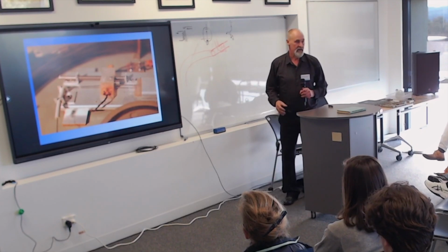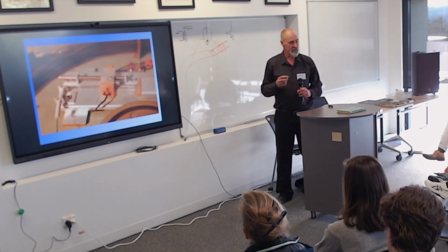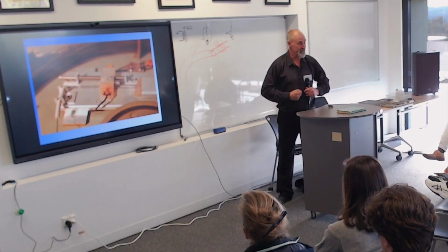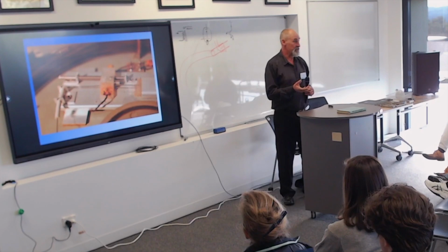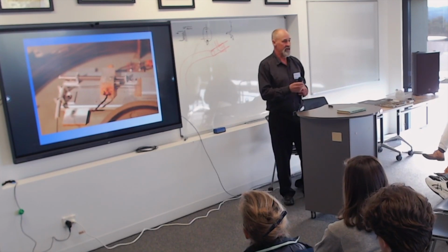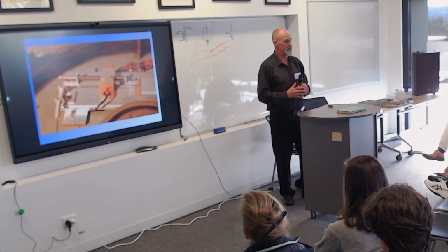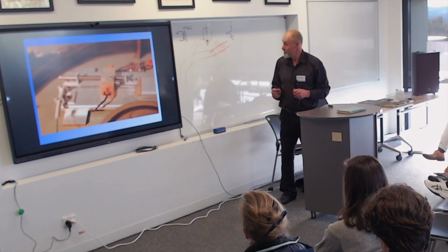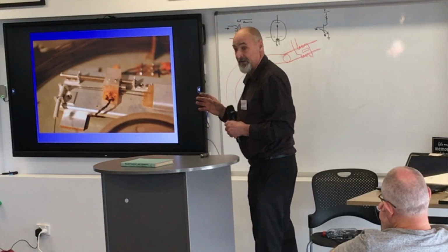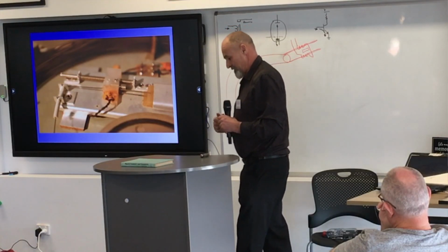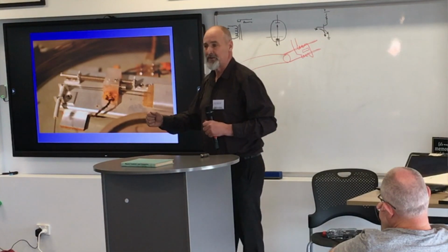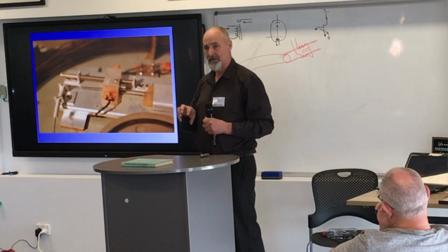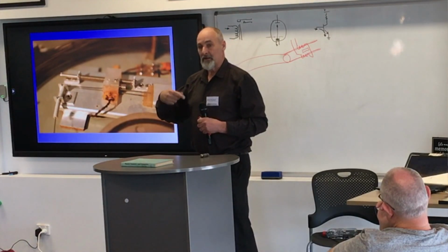Basically, when you apply a magnetic field to some ferromagnetic materials, they go eek and shrink. It's why transformers buzz. People think they buzz because the magnetic field is pushing the plates apart, but it's actually the plates vibrating because they're changing dimension. The Villari effect is when you stress a piece of ferromagnetic material, stretch it, it actually changes the magnetic field around it, creates a small magnetic field that can be detected.